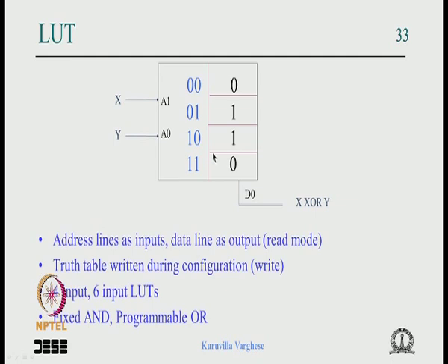When we discussed the PROM, we said that it is an overkill, because the PROM contained a lot of locations. It was a very wide implementation, and it wastes a lot of locations, because for that particular application it was basically using address decoding. It needed only one product term and we were implementing quite a number of them. So that was a waste, but here it is only a few lines and all the functions can be implemented.